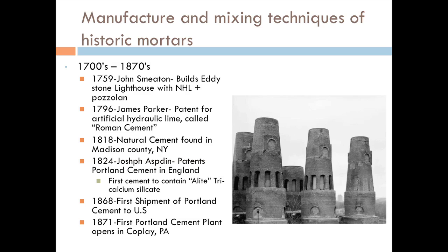He called it Roman cement, which it was called a bunch of different things, and depending on what documentation you look at, it's kind of sketchy where exactly it was used, because Roman cement 30 years later actually means something else. So primary source documents can be difficult. Really the only way to tell is through chemical analysis and what can be inferred through reading.